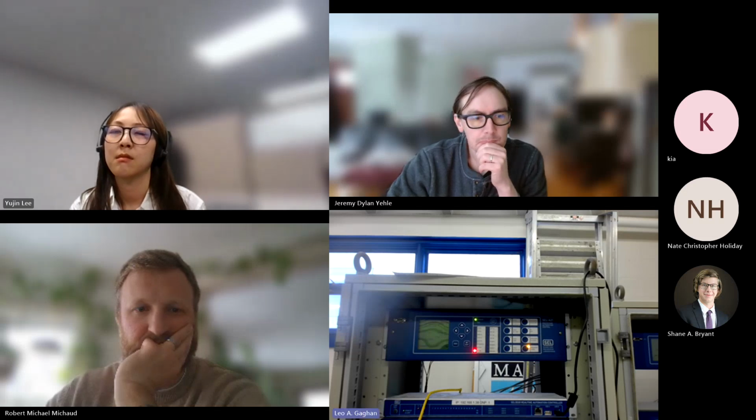Kind of like a lockout tagout, if you would. Okay, so you would put it in hold. No one can open or close the breaker, for safety reasons. So this is just the toggle for the enable.